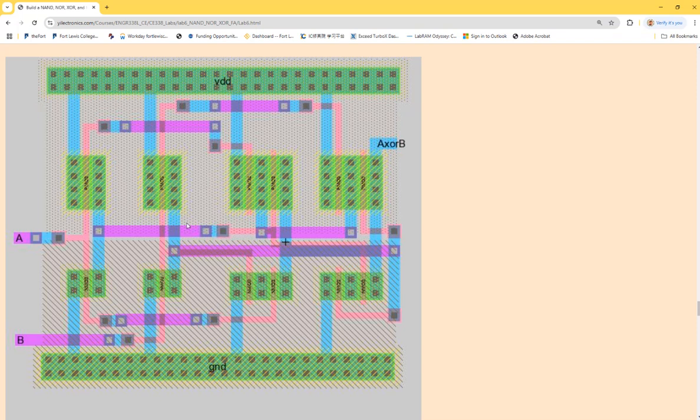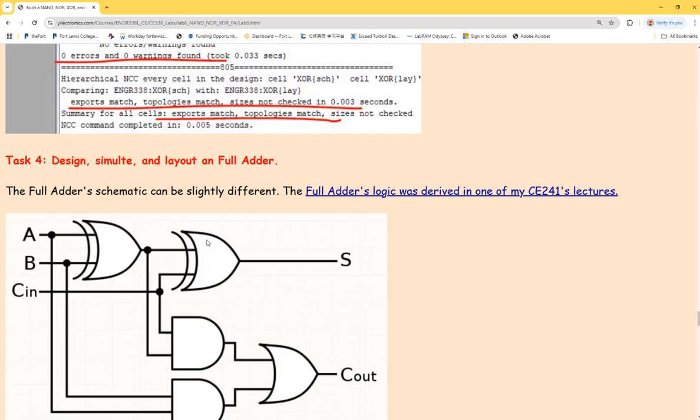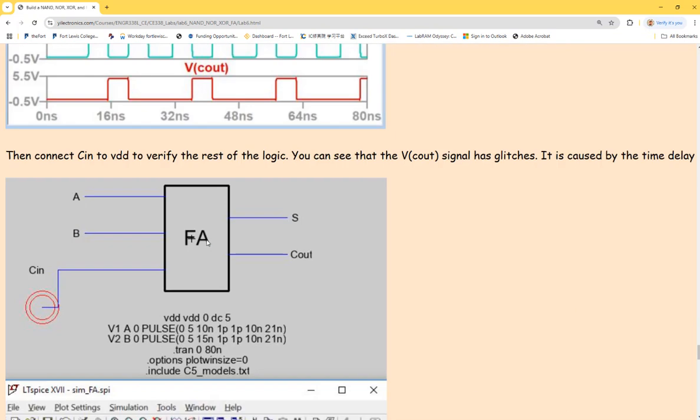See here, it's difficult because all these drains are shorted by metal 1. So in that case, if you want to have any signals being shorted in between these gates, you just have to use metal 2. There's no way that I can use a single metal layer to make all the connections. They are going to be shorted together. Do we need the metal 3 for now? Probably not.